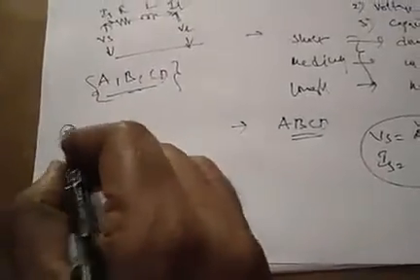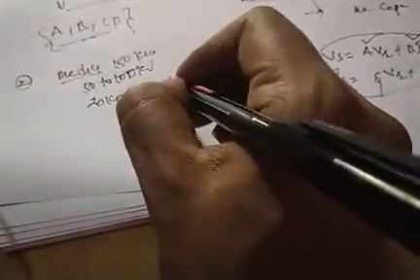the medium transmission line. What is the length of the medium transmission line? 50 to 150 kilometers. Sorry, and what is the voltage it can carry? 20 kV to 100 kV. Definitely the length is larger, so the capacitance effect should be present in the system.